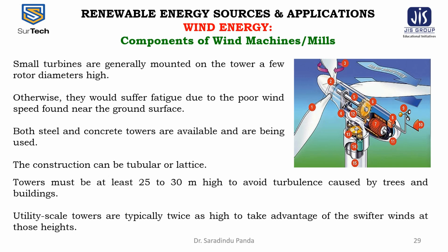Big cranes are generally required to install these wind towers, with gradually increasing tower height. However, new technology is bringing a new dimension to the installation process. Large rotors add to the transportation problem as well. Towers in sections, with the nacelle and rotors moving upwards along with the tower, are among some of the newer developments in wind tower installation. The offshore installation comes with its own challenge and it must be met.